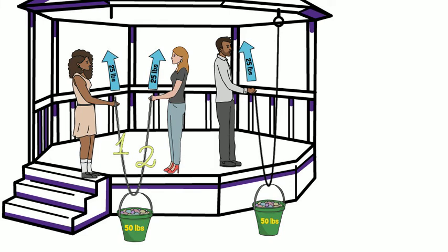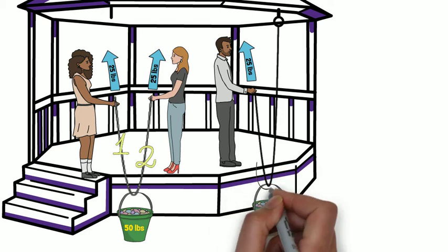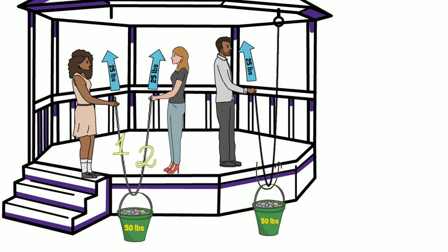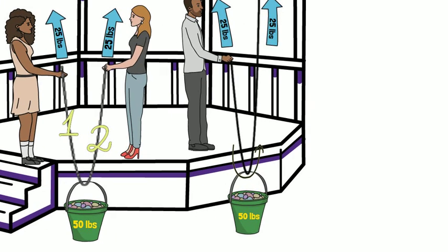If Ron puts 25 pounds of upward force on that rope, the entire length of rope will have 25 pounds of force on it. So in this case, Ron's 25 pounds of force travels around the handle and back up towards the bolt anchor. The effect is that the anchor is holding half the weight of the bucket, while Ron holds the other half. There are two things going on here: load sharing, or weight distribution between Ron and the anchor, as well as a multiplication of forces.